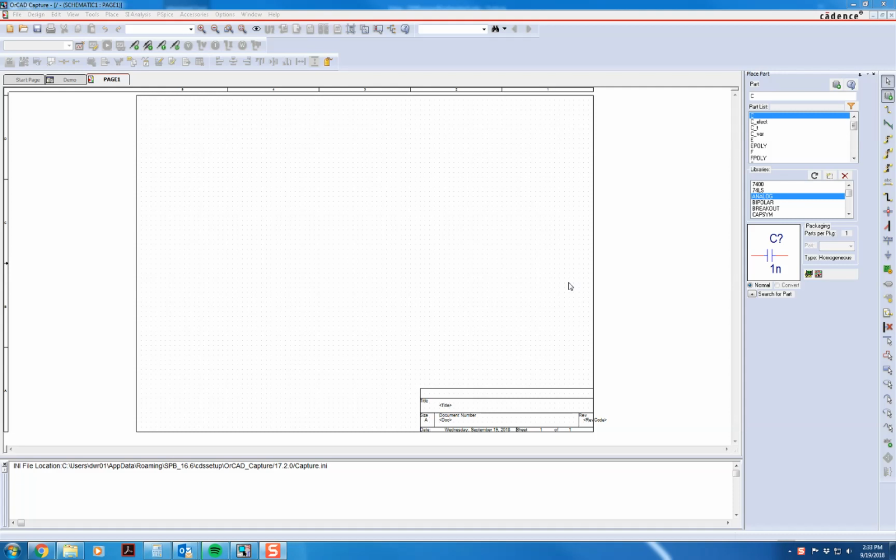Alright, so in this video I'm going to show you how you can simulate dependent current sources and voltage sources. Now these are located in the analog library, which is where of course our resistors and capacitors and other components are located, but they're not given necessarily a very descriptive name here. So I'm going to go ahead and pull several of them in. We're not going to use them all here, but it would be under analog and then E. So maybe it's going to pull in there.